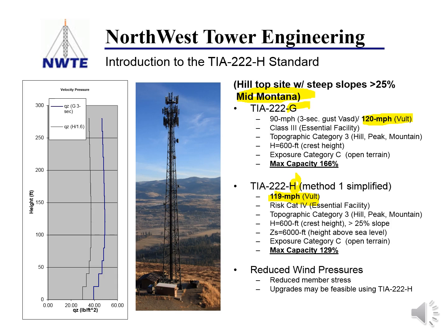But what I do have is this height above sea level. You can see we're at 6,000 feet. So the only real difference between these two in terms of the analysis is to do with the 6,000 feet, and this reduces the wind pressure quite a bit. Here's the wind pressure. As you can see, H over here, G this side.